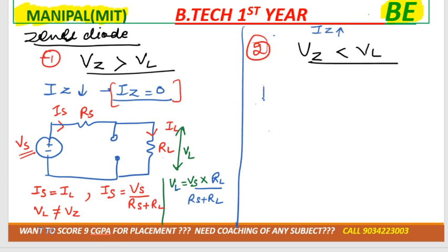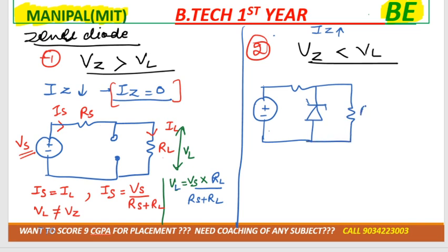Okay, now for the second condition, Vz is less means Iz would be more. Correct? If Iz would be more, then we'll draw the proper standard circuit as I told you, that will have the Zener, will have the load resistance RL, will have the Rs, and this one would be Vs. The current flowing over here would be Is, here it would be Iz, and here it would be IL. So we can say that Is would be equal to Iz plus IL, right?